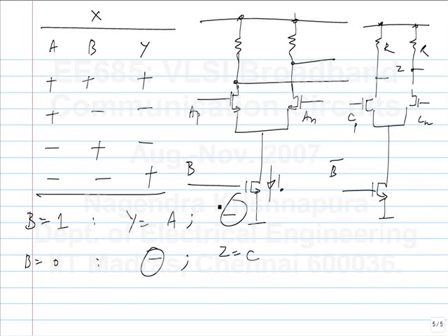So basically what happens is when B is low, this current source is inactive and nothing flows through these resistors. Okay, but that is the condition in which there is some current flowing through this. So I don't use two sets of resistors. I connect these two here. Okay, I connect the two differential pairs in parallel. So now I have a single output Y. I don't have two outputs.